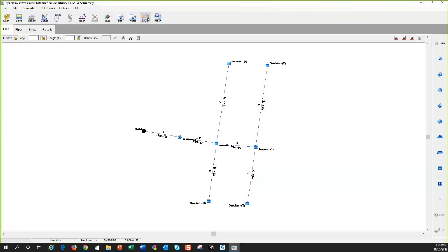You can also send things out as an XML file. When we get to files, you can bring things in from an XML file too, and at one time that was the preferred way of doing things. But I'm showing you the newer workflow and the newer version where you go directly in and out from Civil 3D. And you can also export to a DXF. That's kind of handy if you want to take some of these plots and put it in a format that you could then drop into a drawing and submit.